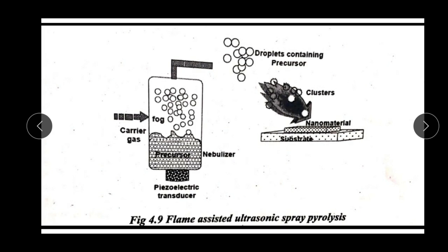The combustion flame synthesis, in which the burning of a gas mixture, for example acetylene and oxygen, or hydrogen and oxygen, supplies the energy to initiate the pyrolysis of the precursor compounds, is widely used for the industrial production of powders in large quantities, such as carbon black, fumed silica, and titanium oxide. However, since the gas pressure during the reaction is high, agglomerated powders are produced, which is a disadvantage for subsequent processing.